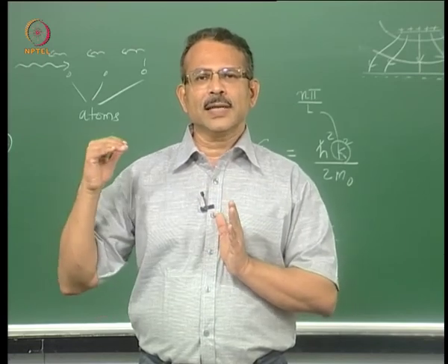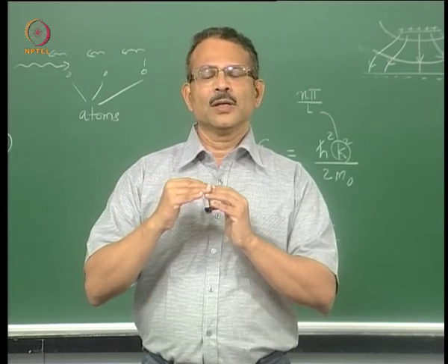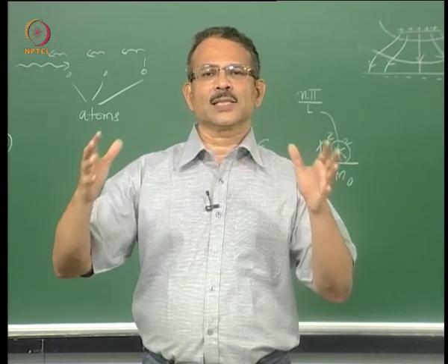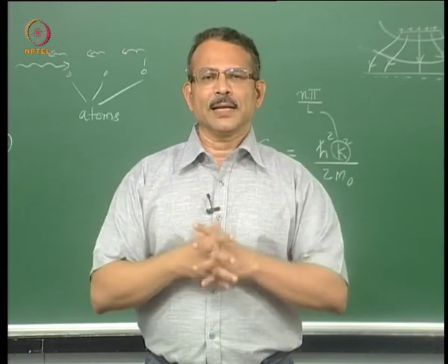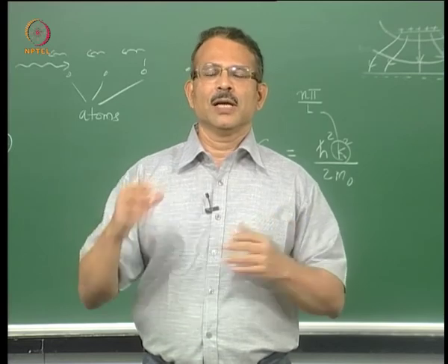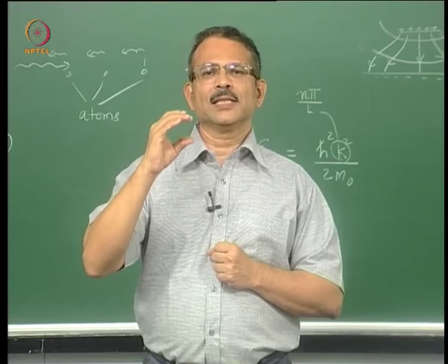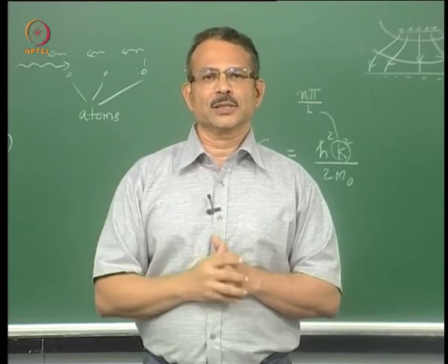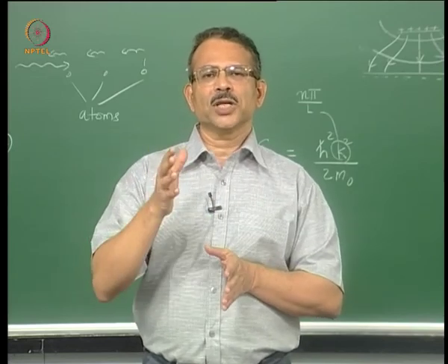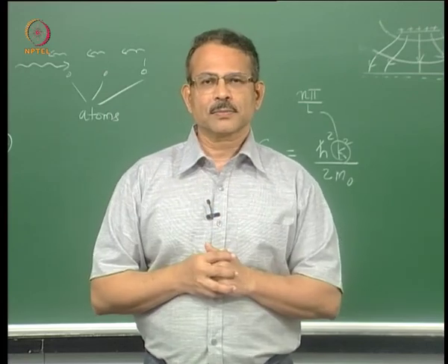In this manner, a discrete energy level of electrons in an isolated atom splits into a number of levels for electrons in a crystal consisting of many atoms. Since these levels are all very close to each other because the number of atoms is very large, we refer to this group of closely spaced energy levels as a continuous band of allowed energies. So, formation of allowed bands is the characteristic of this Bloch tight binding or LCAO approach.